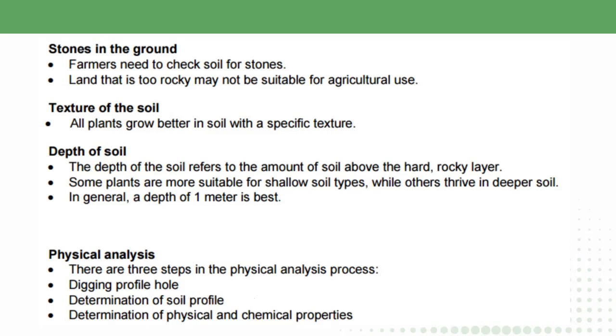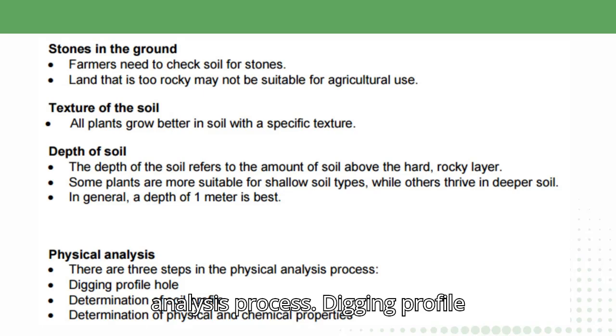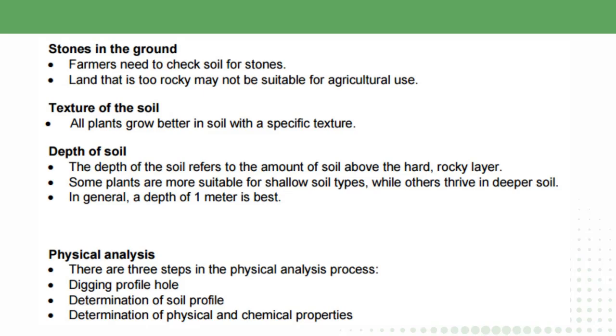Physical analysis. There are 3 steps in the physical analysis process. Digging a profile hole. Determination of soil profile. Determination of physical and chemical properties.